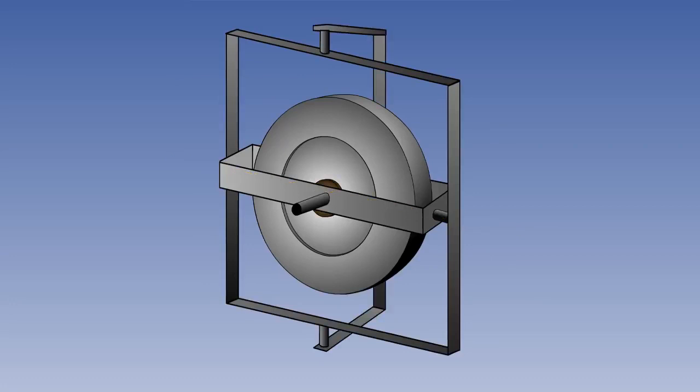Finally, the outer gimbal is pivoted in a housing which is fixed to the aircraft. This allows the housing, and also of course the aircraft, to move around the outer gimbal. The outer gimbal, or second gimbal, is therefore said to provide 2 degrees of freedom. So, we can see that by mounting the gyro within an inner and outer gimbal system, which in turn is fixed to the aircraft, there is total freedom for the aircraft to move around its gyro without displacing it from its orientation in any of its axes.